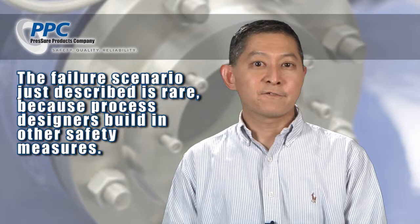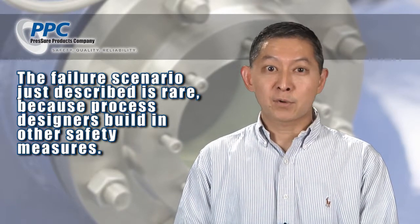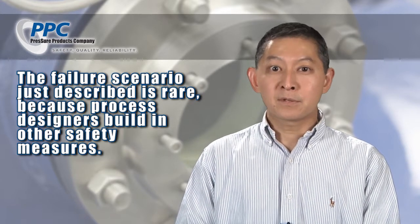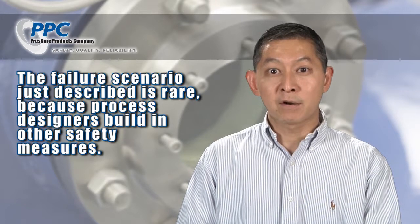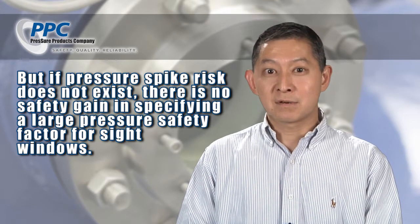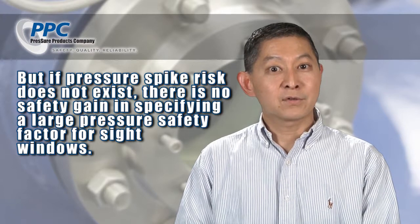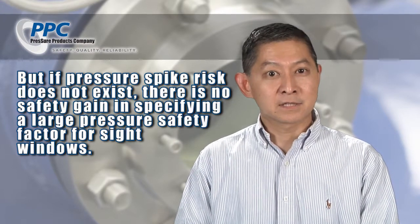Fortunately, these types of failures are extremely rare, but that's because engineers who design such processes are acutely aware of what I just described, so they build in redundant safeties so that the pressure and temperature risks are essentially non-existent. Of course, if the risk of pressure spike does not exist, what safety advantage is there in specifying a side window with a pressure safety margin? You're better off saving your money for some other way that will mitigate a risk factor that actually exists.